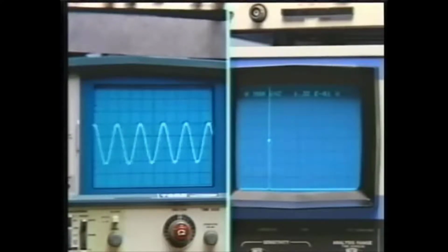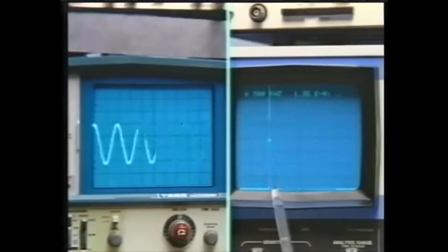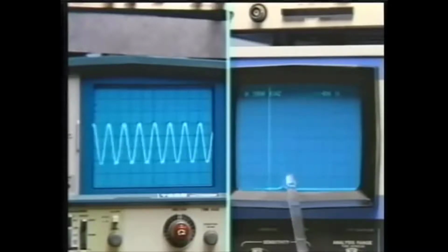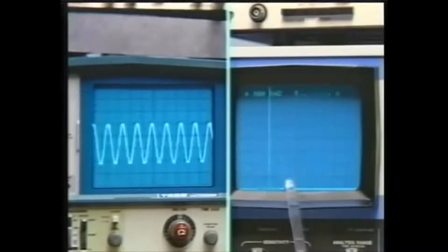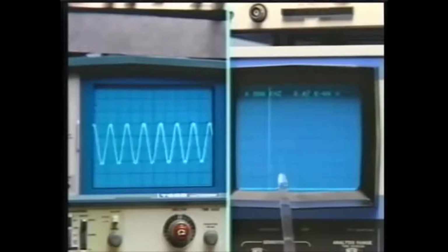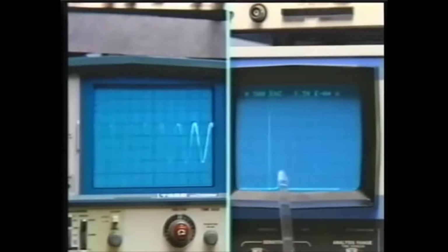Okay. Well, now maybe what we can do is vary the frequency. Let's vary the frequency of the sine wave generator. Maybe also listen to it. I'll turn on the tone. I'll make the frequency higher, and you'll see a correspondence in the time domain. Frequency clearly goes up, and that line of the spectrum also migrates up away from the cursor. Let me just point out again that this is the cursor line. This isn't a spectral line. And this is the frequency content of the sine wave.